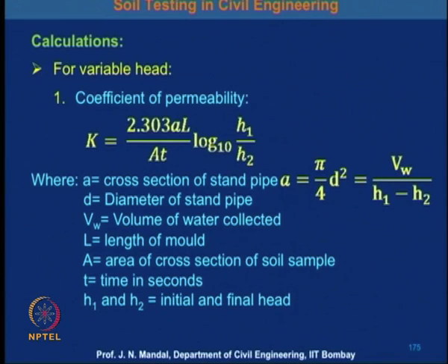And you know the area of the mold and the area of the standpipe, so you can calculate the coefficient of permeability of the soil.